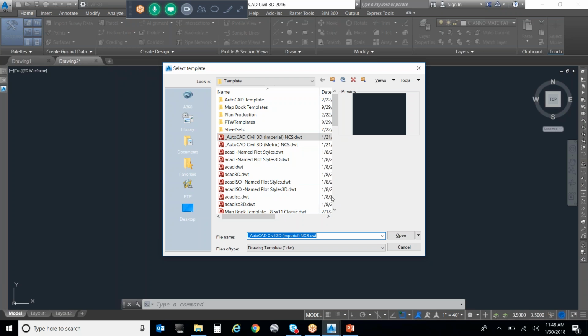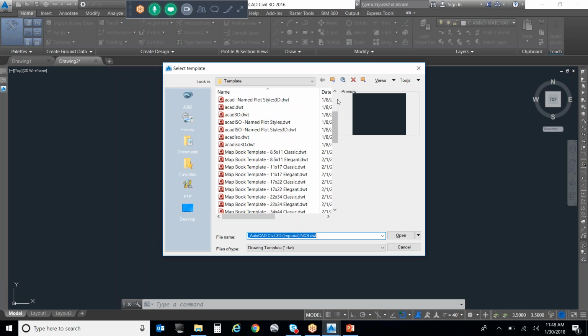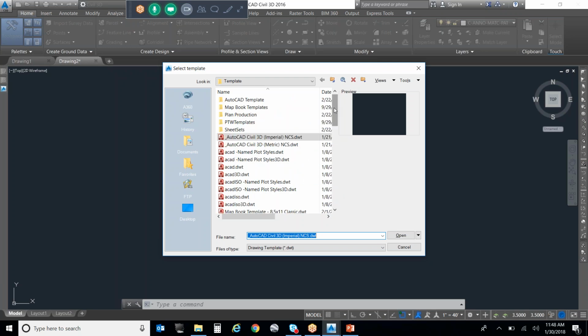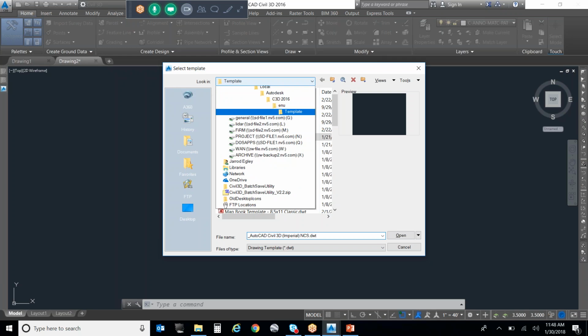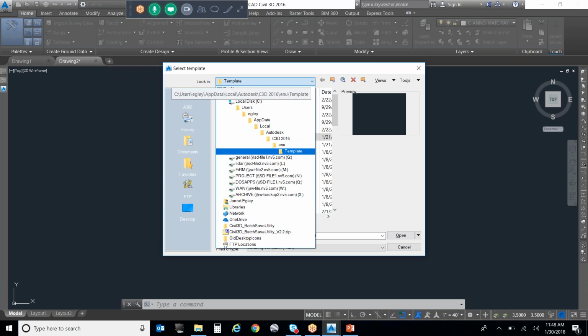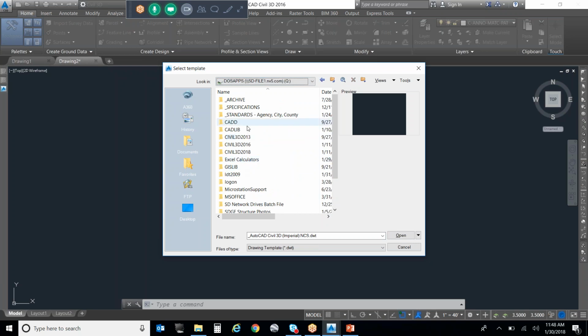And then we introduce a whole slew of issues. One day I got an IM: "Hey, when I create a dimension, it comes exploded. Every dimension I create is exploded." Well, that's an AutoCAD variable that's saved in the file. Whatever company, whatever software created this file, that's how that variable was saved.